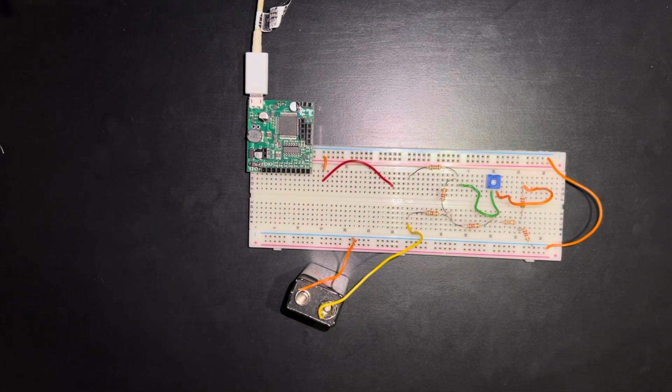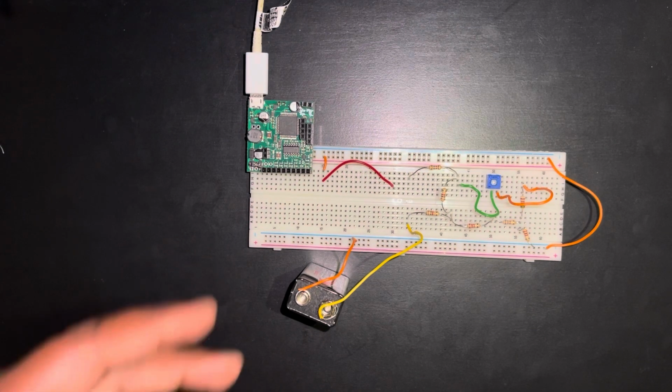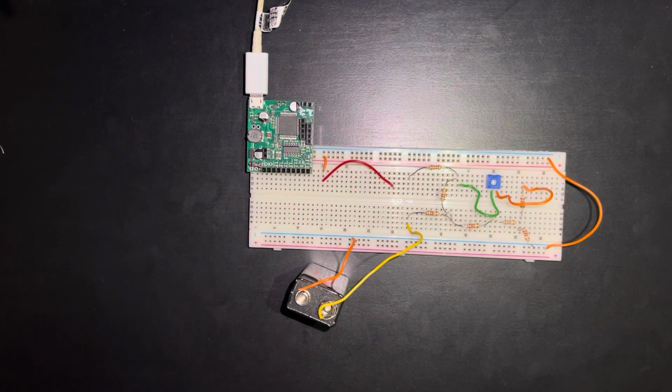Okay, so if it is a lot, let's say 15%, 20%, that means you're doing something wrong. So it's got to be below 10%. That tolerance is acceptable, because we are not supplying exactly 9 volt DC. It's almost like 9 point something, right? So the percentage error is going to be a bit more, but that's totally acceptable as long as it's below 10%. Okay, so that's for superposition.